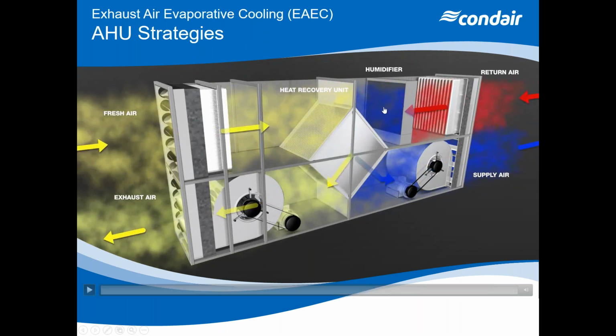So we evaporate as much moisture into the air as we can. So we've probably taken that down from 26 to 19, something along those lines. And then we exhaust that air. So we're cooling, again, one side of a heat recovery unit or a heat exchanger. So our fresh air then comes onto the heat recovery unit, is cooled and goes to our supply air.